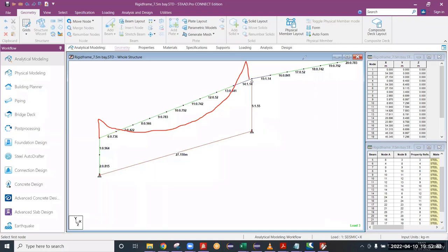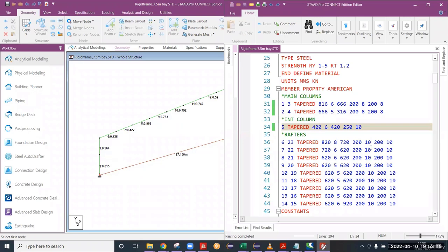So you have to increase the thickness at the bottom, and you can decrease the thickness at the top, because the rafter has to counteract this BMD. It has to be strong at the bottom, and you can reduce at the top. That is the key point you can do here. That is why I'm reducing the top thickness here. Bottom thickness I'm not reducing.